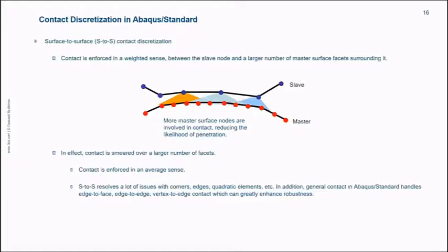So it was the edge to face contact in the general contact that allowed me to pull that disc through the ring, because the edges of the disc were sliding along the faces of the ring, and in a simple contact pair definition, it was having trouble maintaining the constraint with only face-to-face contact.